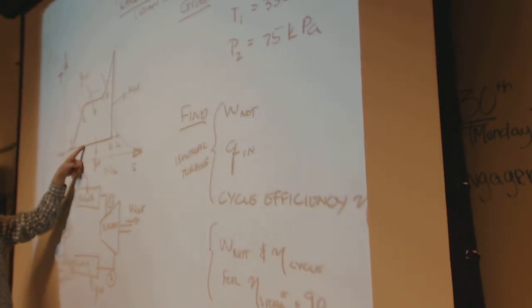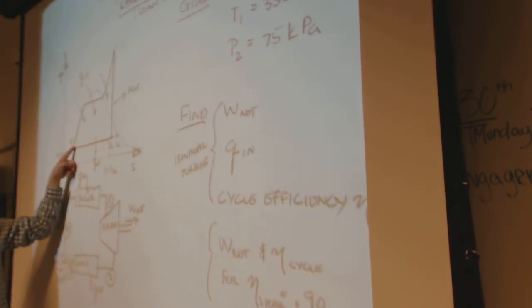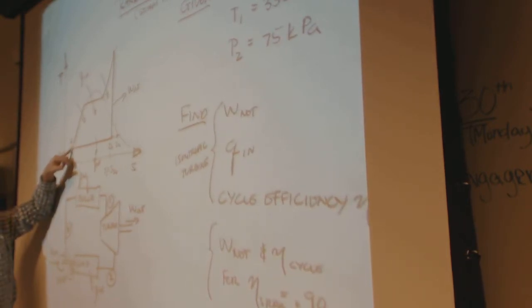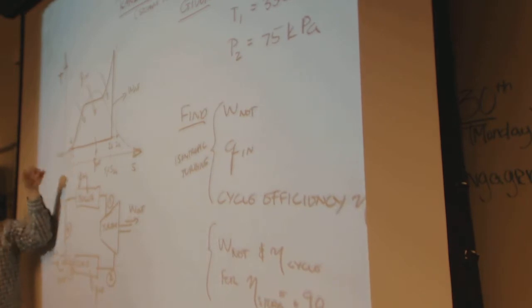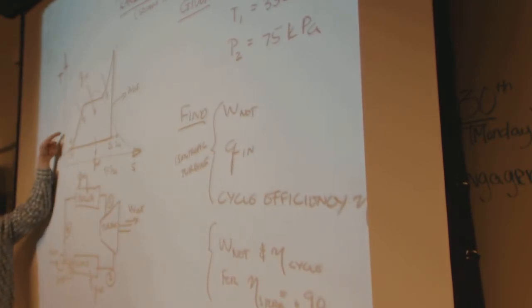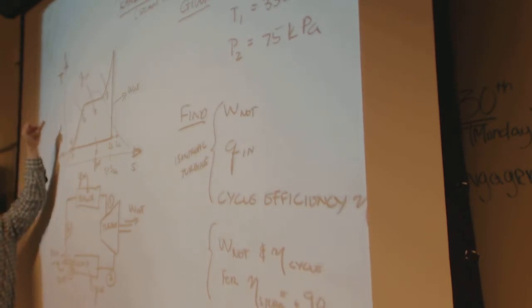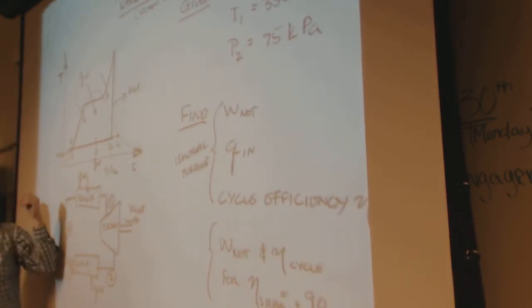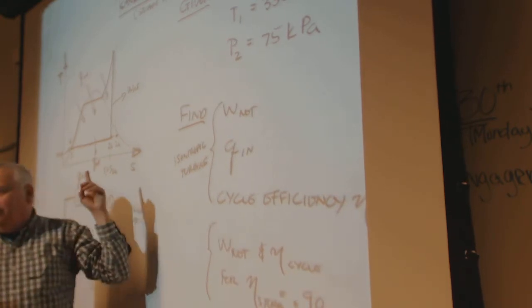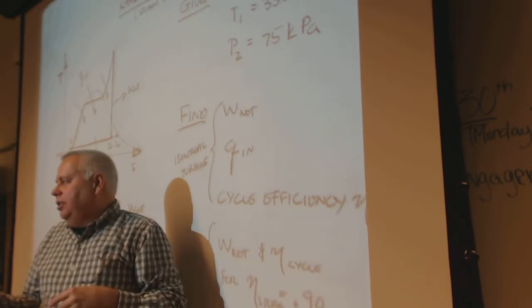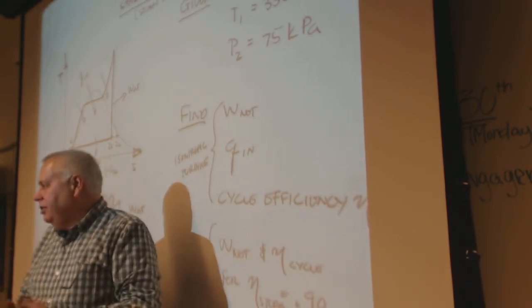This is where the heat comes out. The exhaust is about condensing the steam. Work goes in to the pump. It doesn't really show here because the pump doesn't put any temperature into it, and this is a temperature scale. If this was a pressure scale, you'd see a big bump. If the pump is inefficient, then it will generate some temperature because the waste energy, the inefficiencies, turn into heat.